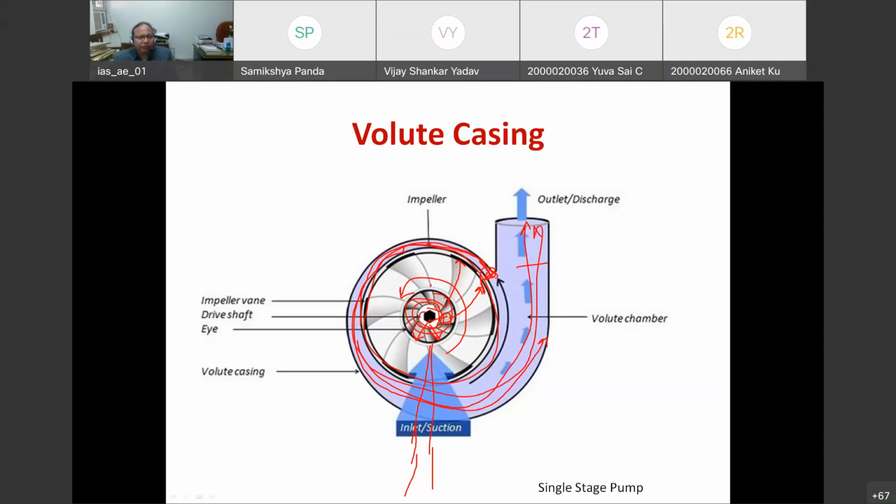Okay. So what happens? Kinetic energy is converted to potential energy. So that's why this water which is coming from this place is coming to the delivery line with less velocity, but it can be lifted to a higher elevation. Its potential energy increases, so that's why we can lift it to the higher elevation with the conversion of the velocity head into the pressure head.